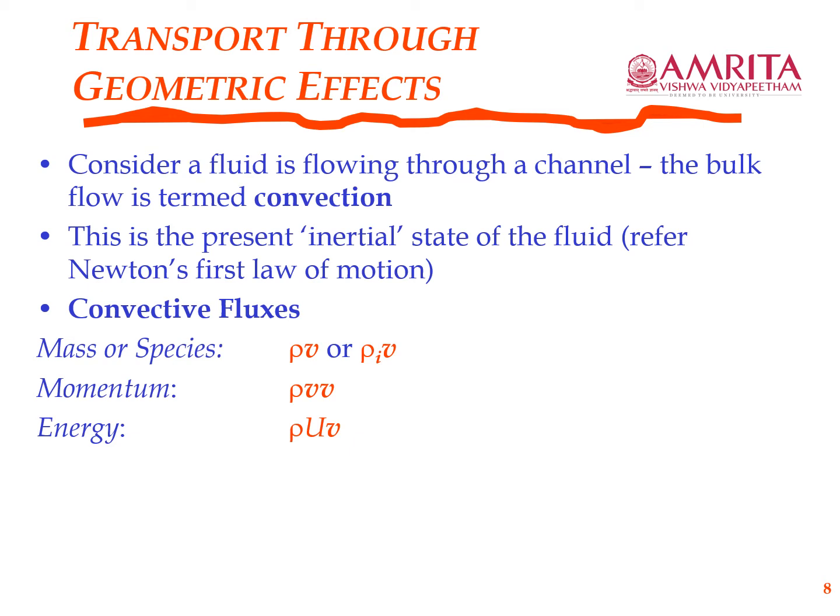That would be U, multiply by the mass, and it will give you joules. Joule per kg into kg should give you joule. Now you're looking at energy per unit volume, therefore you divide the whole thing by volume, so you get rho into U, which is the energy contained in the fluid per unit volume. Multiply that by the velocity, you get energy flux.